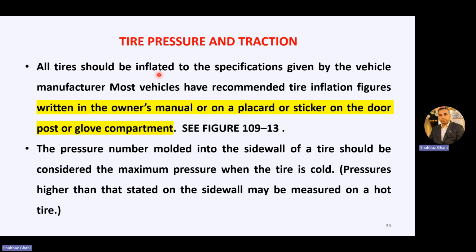All tires should be inflated to the specification given by a vehicle manufacturer. Most vehicles have recommended tire inflation figures written in the owner's manual or on a placard or a sticker on the door post or glove compartment. The pressure numbers molded into the sidewall of a tire should be considered the maximum pressure when the tire is cold. Pressures higher than that stated on the sidewall may be measured on a hot tire. I read again. All tires should be inflated to the specification given by the vehicle's manufacturer (OEM).